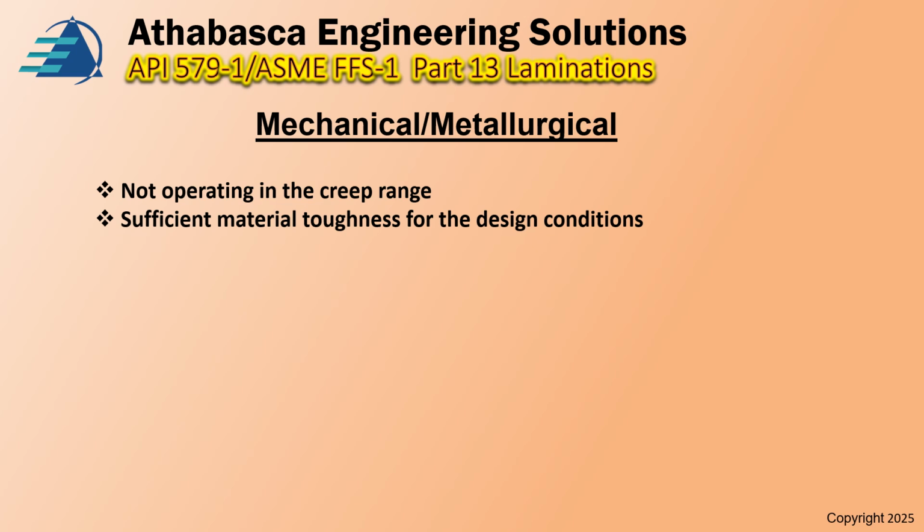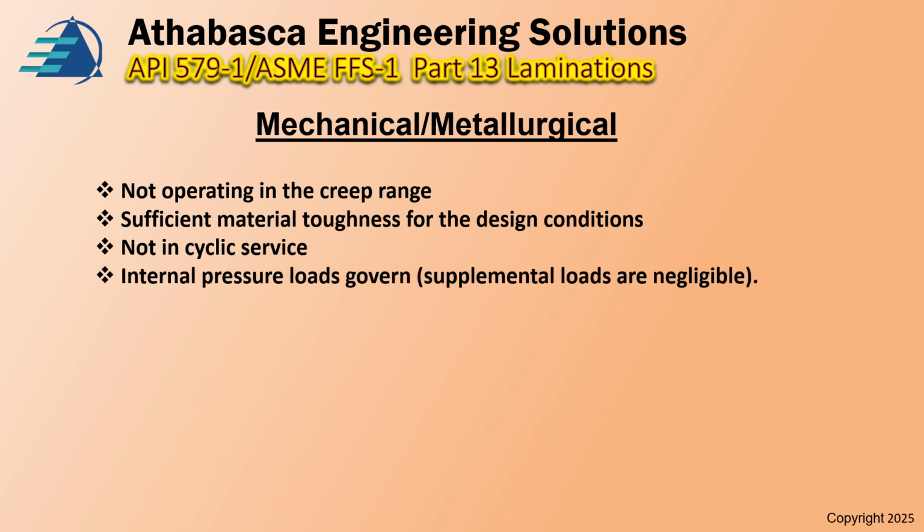The second one is we check to see whether this was in cyclic service, and it's not. The internal pressure loads govern, so the supplemental loads, like bending and so on, are negligible.